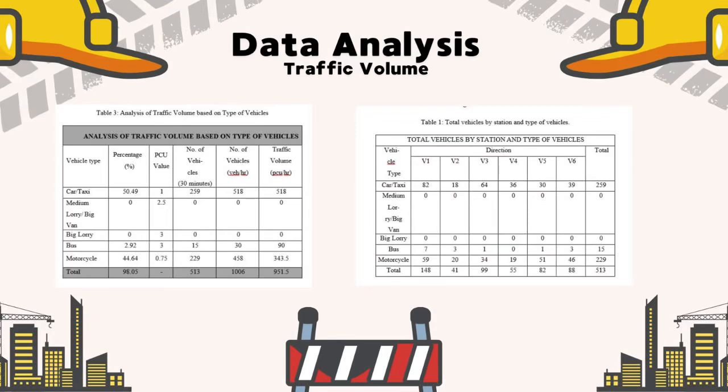Next, I will present the traffic volume analysis. Based on Table 1, a total of 513 vehicles were recorded during the 30-minute survey. Cars and taxis had the highest number with 259 vehicles, followed by motorcycles with 229 vehicles. While only 15 buses were recorded, no heavy vehicles such as lorries or big vans were observed. For the traffic direction, V1 recorded the highest traffic volume with 148 vehicles, while V2 had the lowest with 41 vehicles.